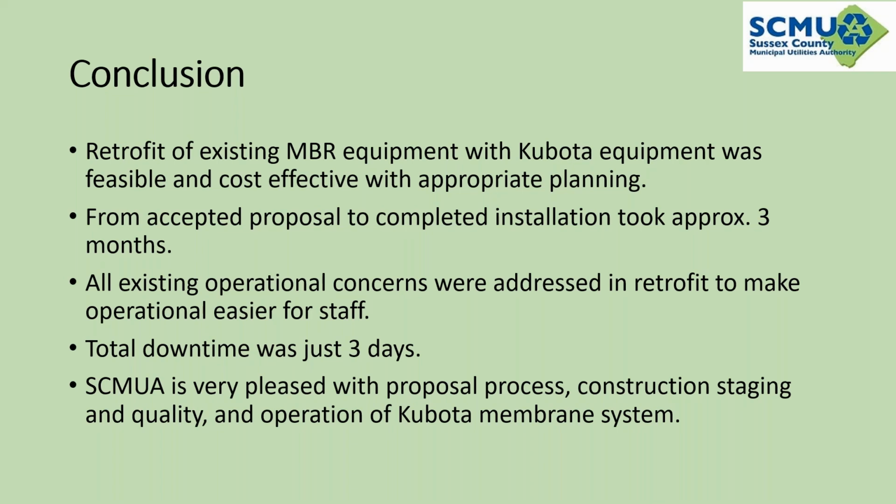So we haven't seen any decrease in permeability or increase in transmembrane pressure that would require it. But again, the intent is to maintain this system for at least its 10-year useful life.